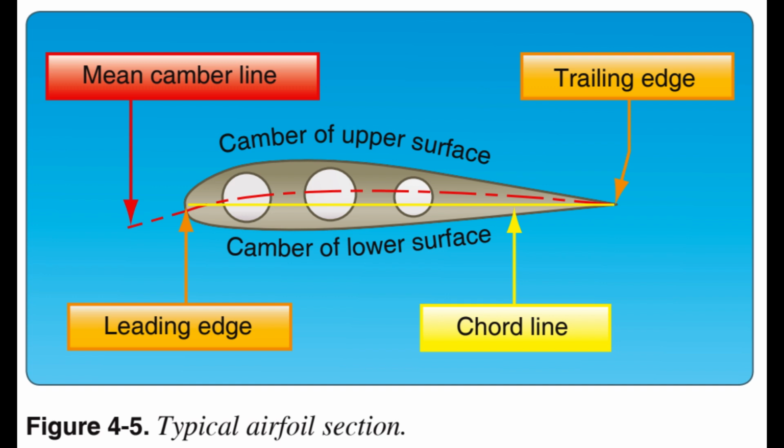Many thousands of airfoils have been tested in wind tunnels and in actual flight, but no one airfoil has been found that satisfies every flight requirement. The weight, speed, and purpose of each aircraft dictate the shape of its airfoil. The most efficient airfoil for producing the greatest lift is one that has a concave or scooped-out lower surface. As a fixed design, this type of airfoil sacrifices too much speed while producing lift and is not suitable for high-speed flight.